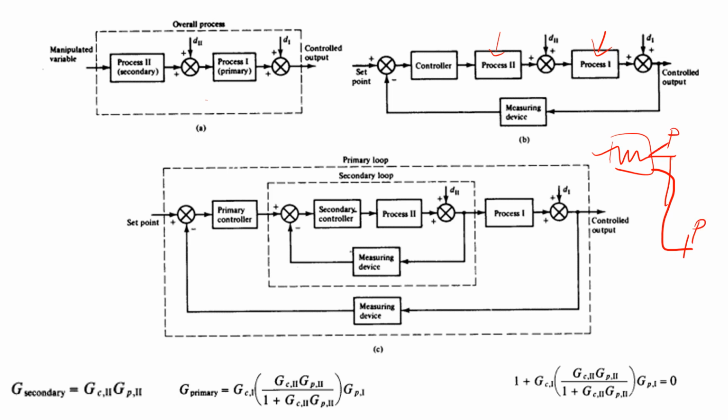Okay, so the temperature you're going to maintain, this is the main process, so that is process 1. And then in order to control this process, we are going to take this control process 2. So that is your fuel system, the secondary process. So we take the process and we have only a common controller. This is normally a feedback.